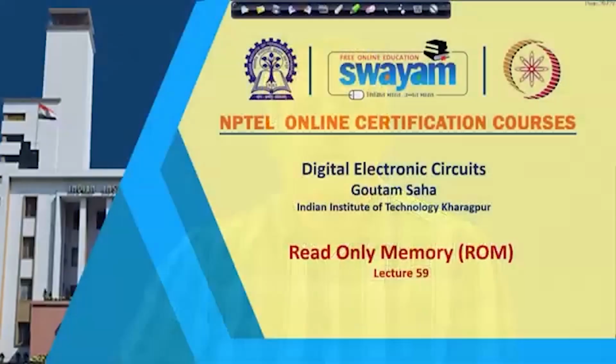Hello everybody. In earlier classes we had seen random access memory, which is also read-write memory. So, the user can write as well as read information from that memory block. In today's class we shall look at read only memory. From the user's point of view, reading will be done multiple times, but writing is to be done by the developer by a certain mechanism, or writing will be done at the factory end.